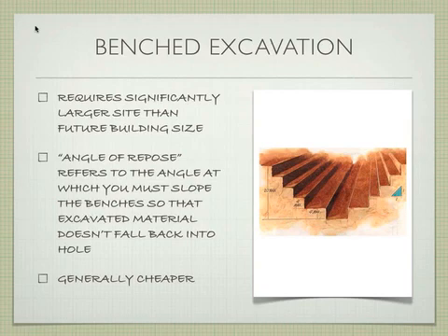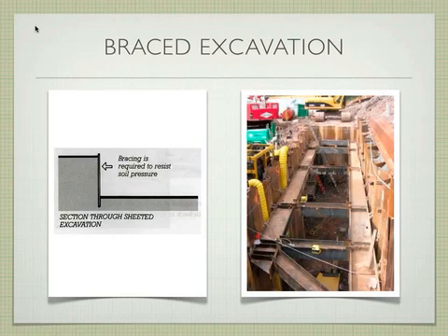Okay? Generally, this type of excavation is a lot cheaper than the other types of excavation. So if you can get away with it, you're going to prefer to do something like this. Okay? The problem is that a lot of times we're building a building where we don't have a really big site. Okay? Sure, if you're building your house, right, or you're building some kind of a tilt-up construction somewhere, you have a lot of space around you. Not that big of a deal, right? You can do that kind of an excavation.